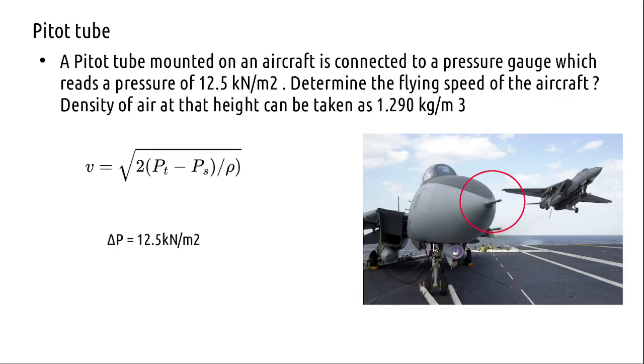So here this Pitot tube is used to find the velocity of the fluid. If you recollect the Pitot tube, it's a tube like this. When the air strikes this front part of the tube, it is going to be at standstill, that is, it is a stagnation. So you are going to measure the total pressure, PT, and this inner part of the tube is connected to a pressure transducer. The outer part is called static pressure. So you have a static ring. Those tubes are connected to another pressure transducer, or still better, you could connect it to a differential pressure sensor.